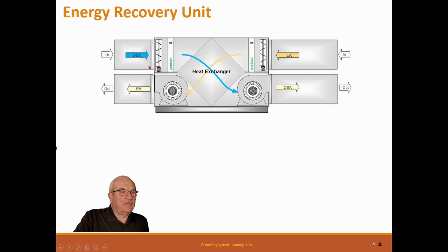The system basically has a makeup air fan that draws air in across the isolation damper and across the filter into the unit. And this is an exhaust fan. It basically draws in the exhaust airflow past the isolation damper, across the filter, and outside. Now the filters are here actually to protect the heat exchanger. If you didn't have this filter, the stuff coming out in the airstream would actually stick on the supply side of this and would clog it.